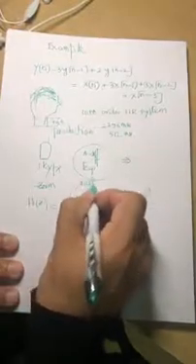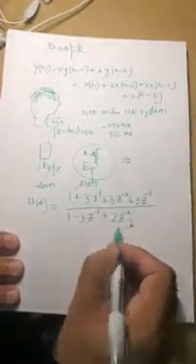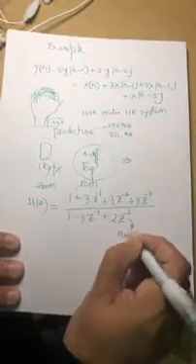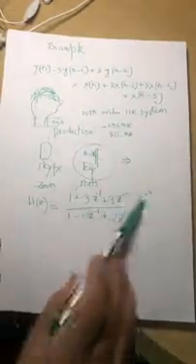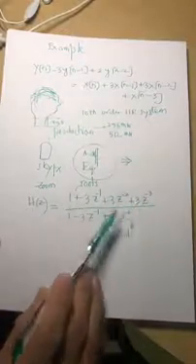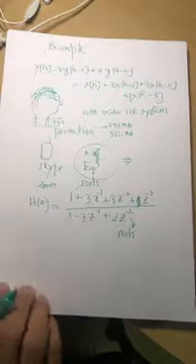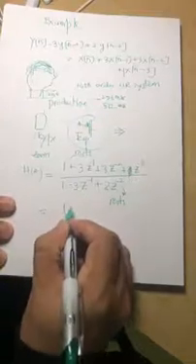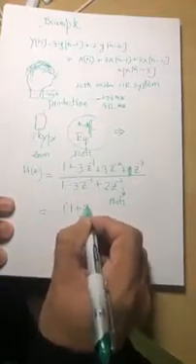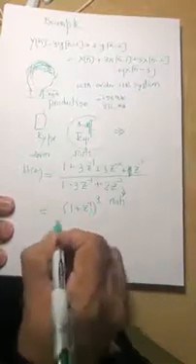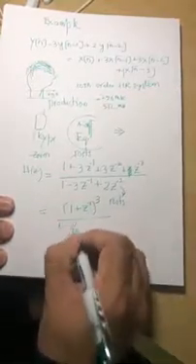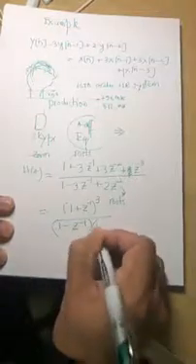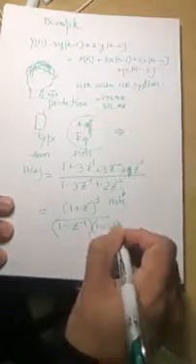Now you need to find the roots. There is a function in MATLAB which you can use to find the roots; otherwise it's a little cumbersome process. Sorry, there is no 3 here, it is 1. If you find the roots of the system, you will figure out that the numerator is 1 plus z inverse raised to the power 3, divided by 1 minus z inverse times 1 minus 2z inverse.